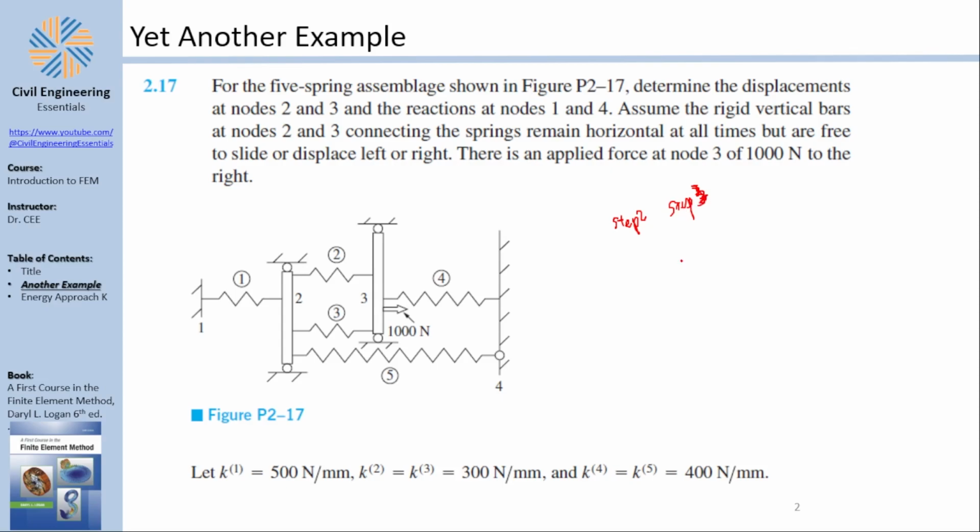The reason those are missing is that for a spring, what is our mission objective? Our objective is to find a vector F that equals a stiffness matrix K multiplied by the displacement matrix, let me call it D for now. And truth be told, for a spring this is ready, because according to physics, a spring force F equals K multiplied by X. So there is no need to assume any displacement or stress relationships.